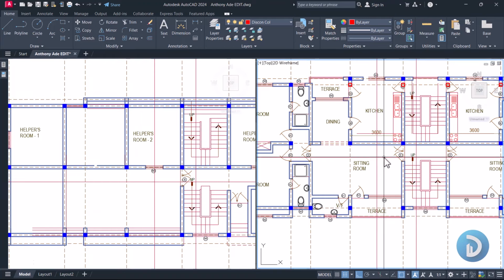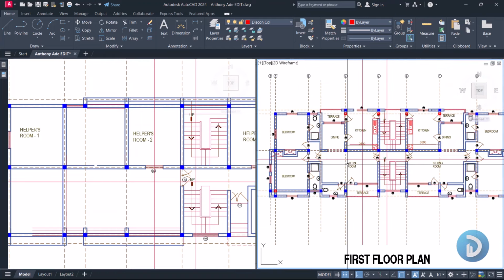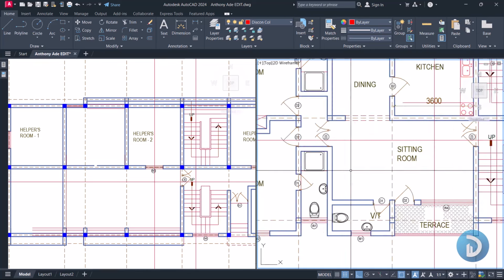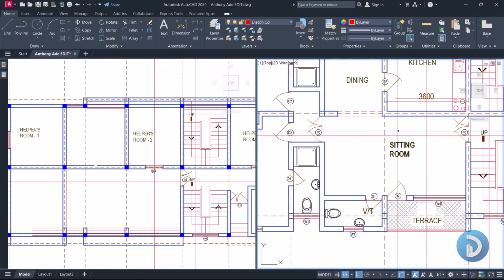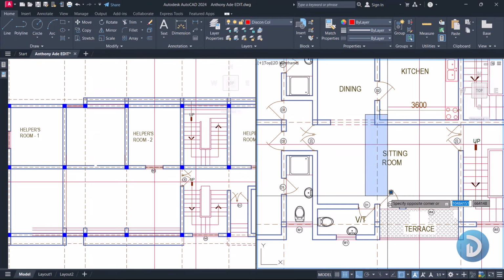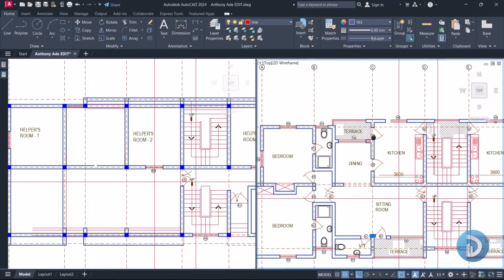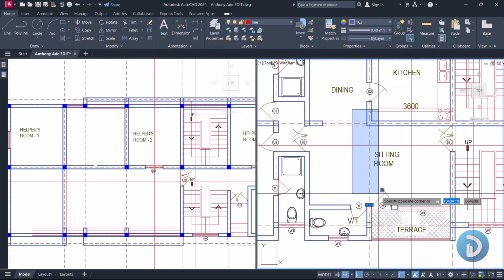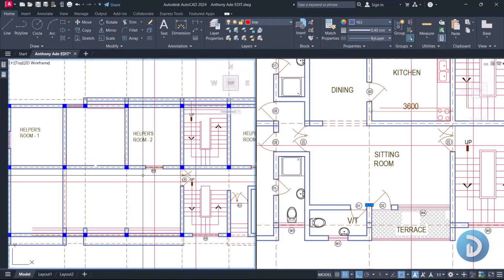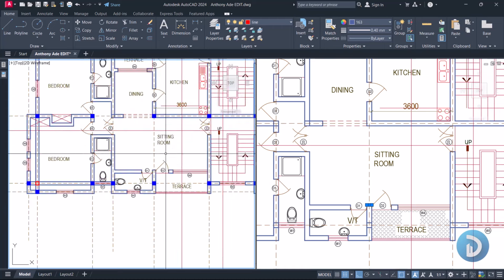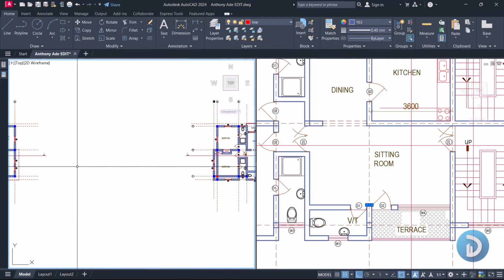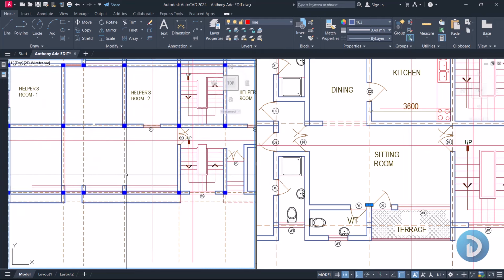But if we get to the second floor and we have this same sitting room area, let's check that out. When we get here and we have this same sitting room area, we can no longer run a beam from grid line C, because if we run this beam on grid line C, they will get to see it when they are sitting at this sitting room on the first floor. Okay, so for this very first set of beams, we can as well ignore and play with it, because this part is a car park.